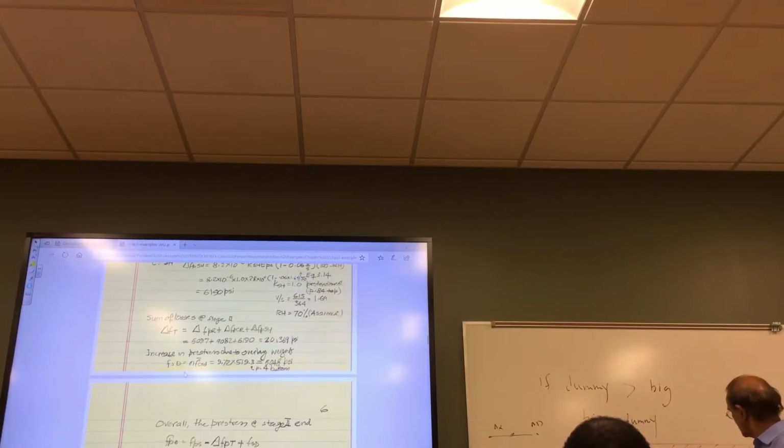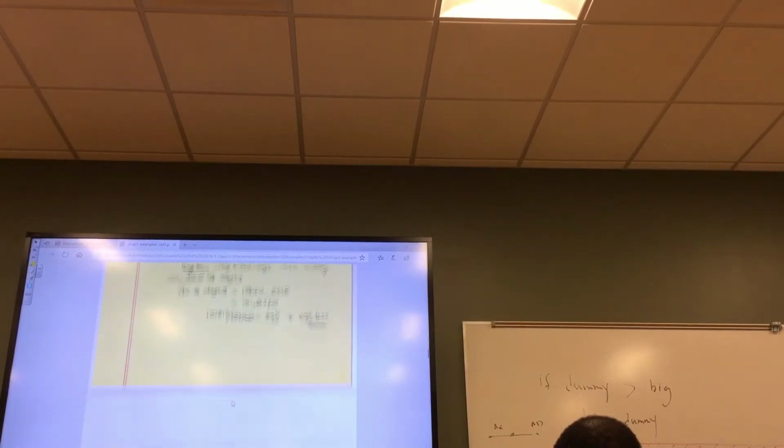Up to the point where you have allowable stress here, the concrete is behaving more like steel. It is not linear, but it is under compression. It will bounce back if you took off the load, except for creep, for example. All right, I wanted to make sure this is not lost.